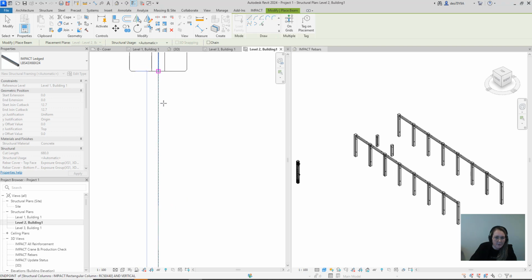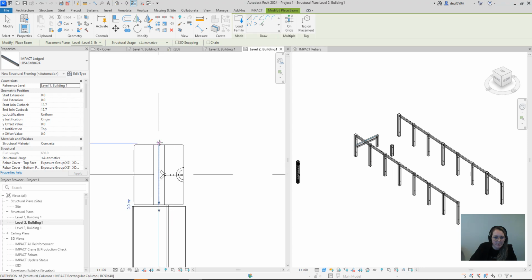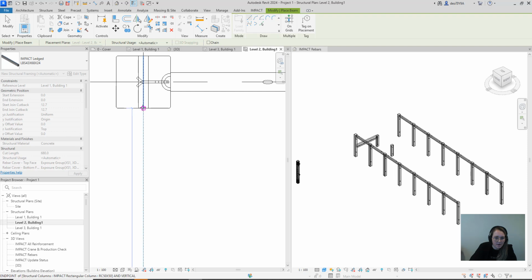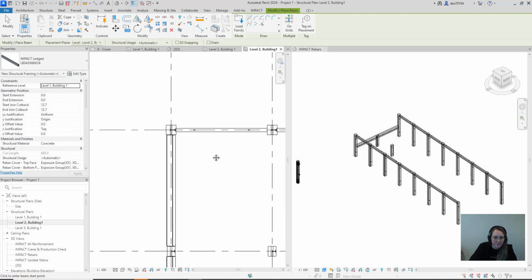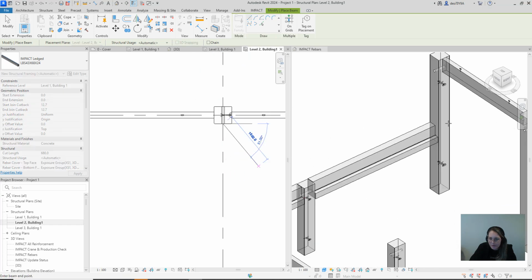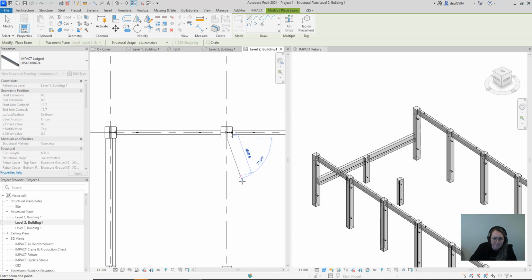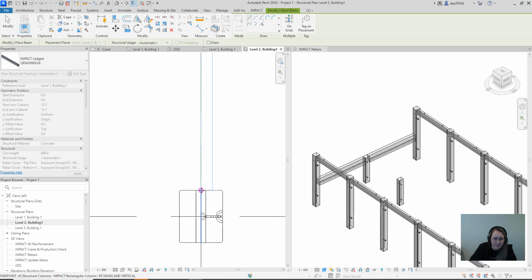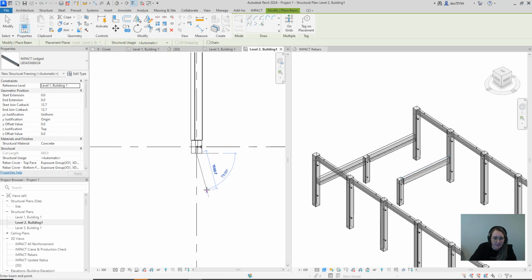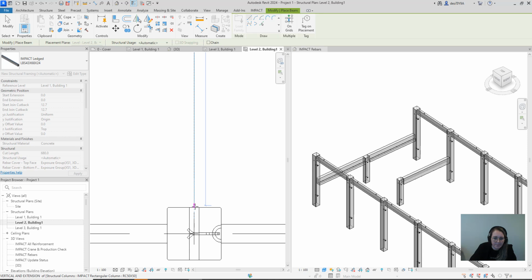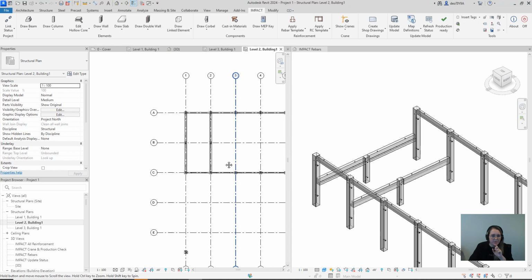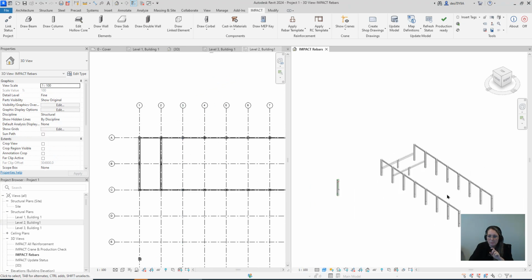These are going to be the ledge beams on which we're going to place our hollow cores later on. Okay, good. Then let me see. Yeah, it looks okay. It's important that we draw them in the correct direction so that we can later support the hollow cores on them. Good. So far, so good. We're ready to jump to the corbels.